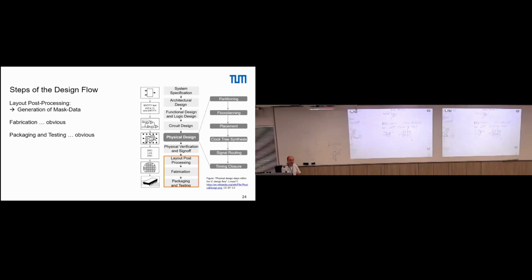From a circuit-level perspective, how this is implemented on FPGA is highly protected IP, but to the best of our knowledge, there are some patents which go in this direction, it looks like this. You have a fixed-depth multiplexer tree. In the case of Xilinx FPGAs, it's usually 6 levels.